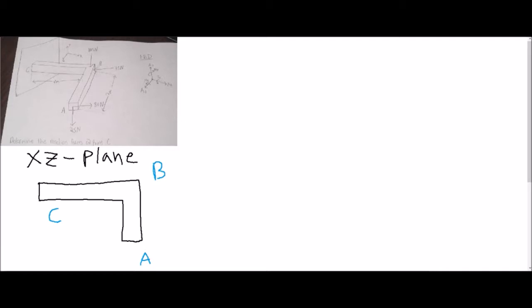Okay, so now we're going to do the forces that we can see. So let's start with point C. From the top, we were able to see Cx. We're also able to see Cz. And let me draw the coordinate system, so this is x, and that's z, based on the coordinate system we have on the drawing. Since we're looking down, we can't see the reaction force acting in the y direction at point C. At point C, we also can see the moment. So I will indicate that right here. And that's going to be the moment in the y direction.